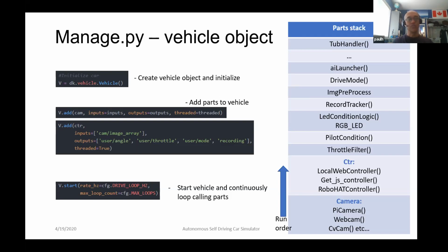So normally you would write the image, which is a separate file, and then as part of the control record, you would write your steering and your throttle. And also it writes in the time in milliseconds, but you can also write in other values. I think if you had an IMU, for example, you could write your IMU accelerometer and gyroscope values into your record as well. So that's how you can go look in there and specify what you want to write into your control record.